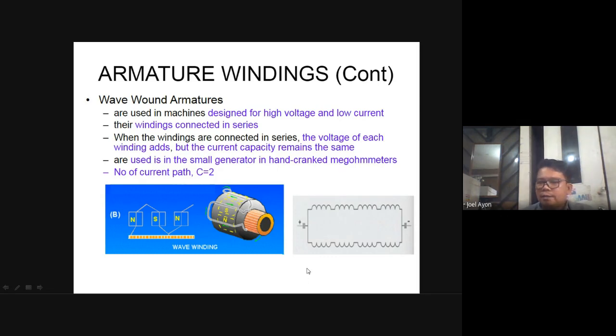Remember what we discussed on the principles of series and parallel. Once the coils or resistors are connected in series, the current is the same. You still remember? Then if it is connected in parallel, the current will increase. It adds up the current. Do you still remember?